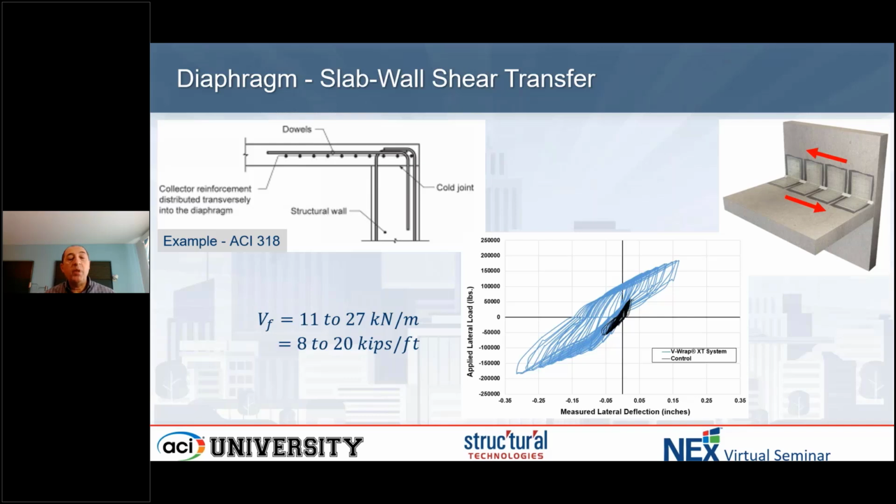For example, we have coupling beams, right? We have shear walls and we have coupling beams in between that are subject to high shear, right? And also bending forces on them. We have done tests, and others have done tests, that show that you can increase the shear capacity of coupling beams and increase their flexural capacity. Things to consider for elements like coupling beams is you need to fully confine the section, because that high movement, high shear, high bending will basically create a lot of cracking in the concrete. So full confinement is required.